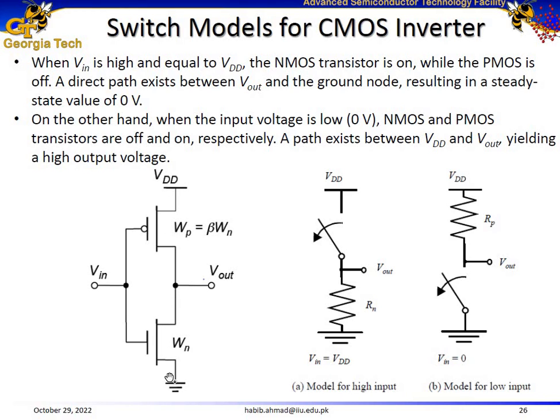And Vout is connected to ground, but we already discussed that these transistors, because of the current flowing through the channel, and that channel current is proportional to the voltage, have a certain amount of resistance as well. So Vout is going to be connected to ground, but via a certain resistance of the N channel. All right, Vout is connected to ground via a certain amount of resistance.